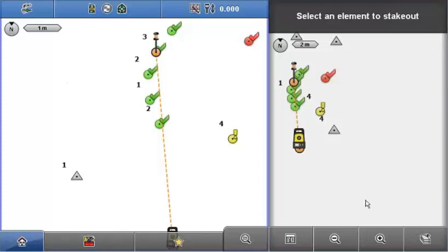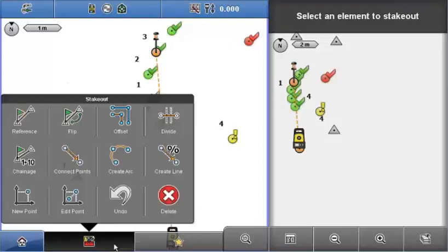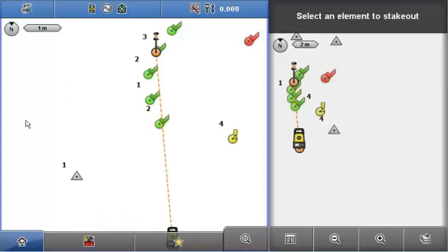One further orientation option is shown in the toolbox, and that's the option of staking with reference to a line. That's here. The in and out values to the point will be given relative to the orientation of a line that you define on the screen. But I'll move on now to talk about staking lines very quickly.